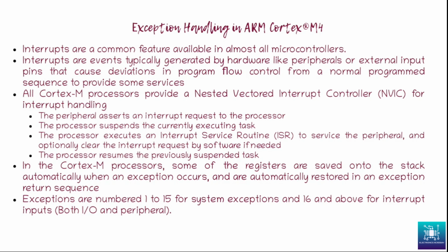Say if you are doing assembly programming, in that case, you would need to save these registers on your own before moving on to the interrupt subroutine. In the case of Cortex-M, that is not the case. The saving of a few registers which fall in the AAPCS is done automatically, so you are spared of that burden.